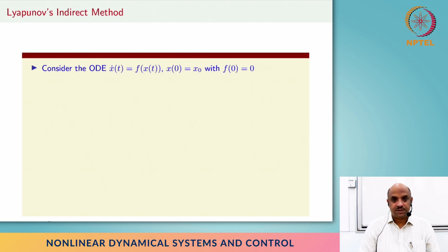So where does this lead us? That's just consistency between our definitions of nonlinear stability and linear stability, and we got these results. But the nice thing is that we can actually say something about nonlinear systems. Why is that the case? Because if the function f is well behaved, then it can be approximated by a linear part Ax plus some nonlinear part, where the nonlinear part is very small close to the equilibrium point, right? That's coming from your Taylor series approach, right?